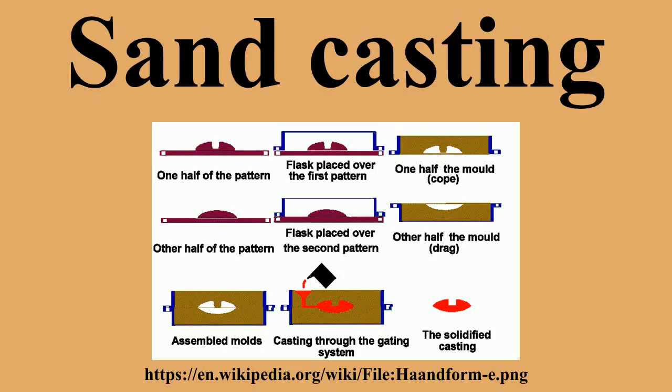Other advantages include no moisture-related defects, no cost for binders, excellent sand permeability, and no toxic fumes from burning the binders. Finally, the pattern does not wear out because the sand does not touch it. The main disadvantage is that the process is slower than traditional sand casting, so it is only suitable for low to medium production volumes, approximately 10 to 15,000 pieces a year. However, this makes it perfect for prototype work, because the pattern can be easily modified as it is made from plastic.